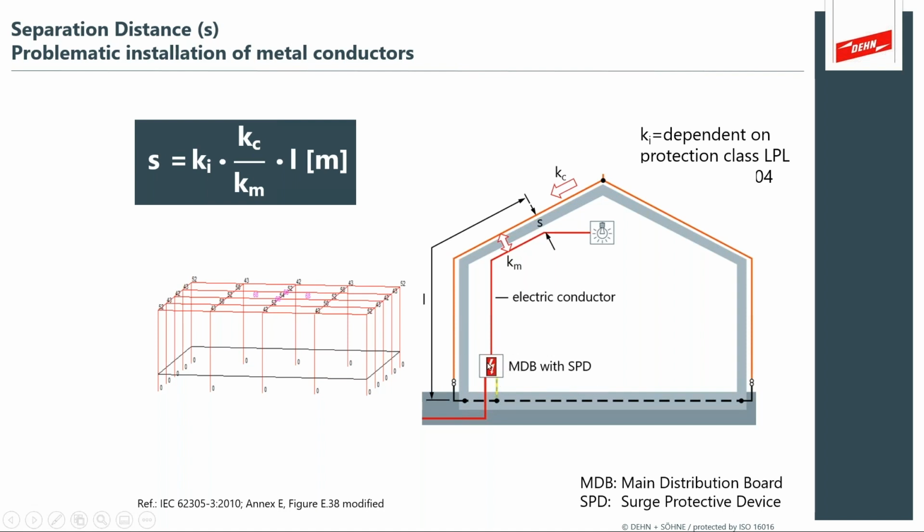So here we have a nice illustration with that master distribution bar, the MDB panel, for instance. But at that panel will also be a master ground bar. And at that master ground bar, we'll want to look for surge protection devices, because even though you haven't flashed over, you can still have voltages build up in these electrical systems. And that's what the surge protection device is essentially achieving.